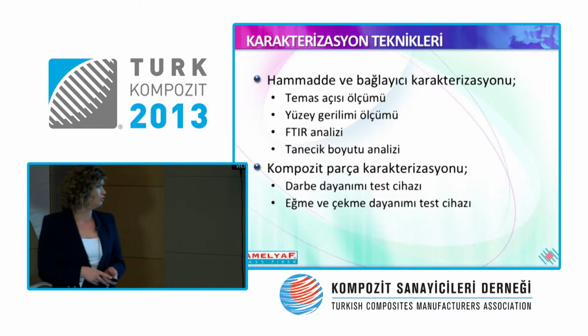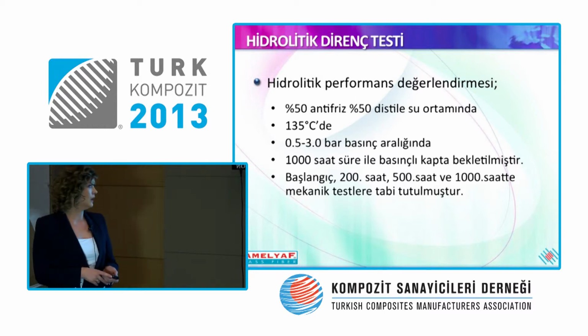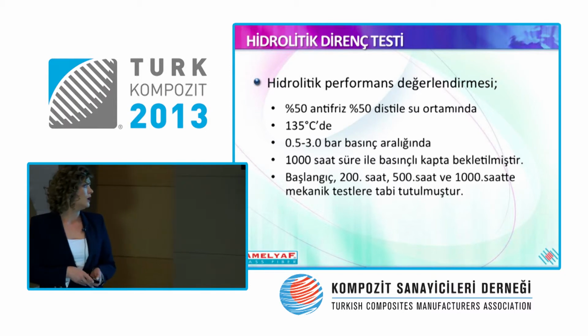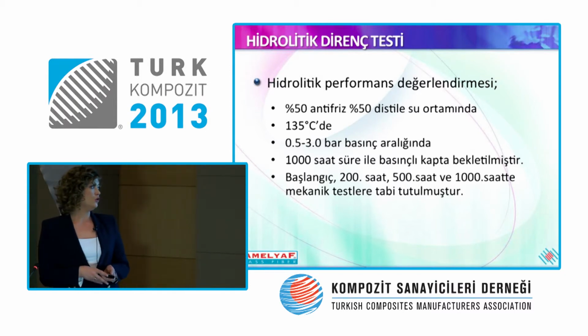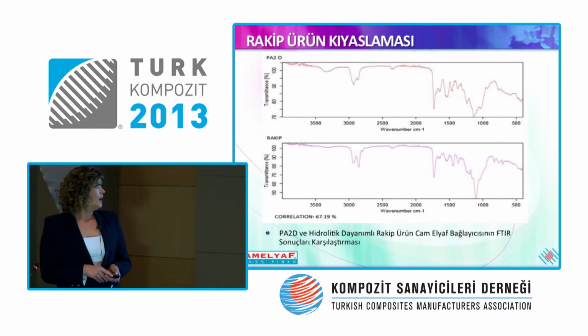For the characterization of composite parts, we use test devices for impact resistance, and we also use test devices for bonding and tension. In the hydrolytic performance evaluation, at 50% antifreeze, 50% distilled water environment, at 135 degrees centigrade, we had a test that lasted 1,000 hours at an interval of 0.5 to 0.3 bars.